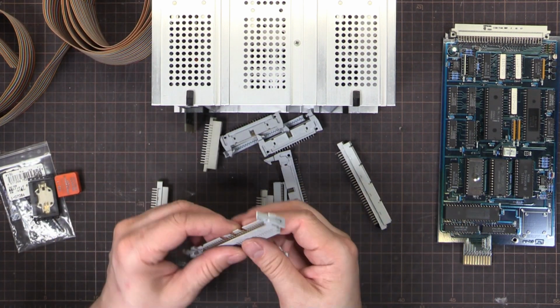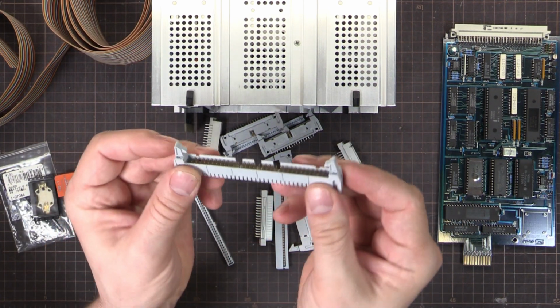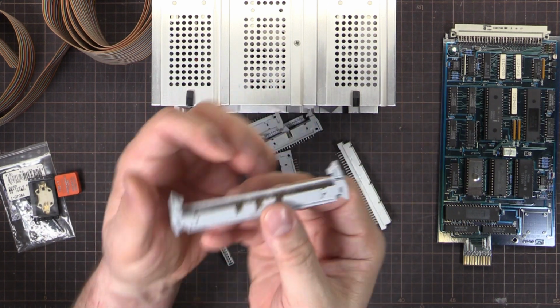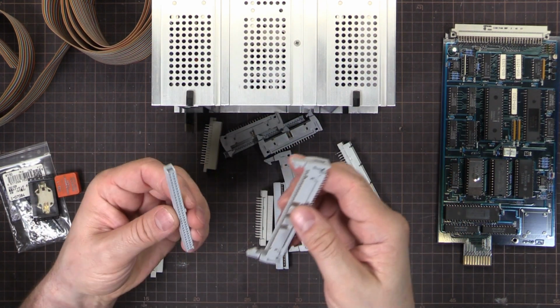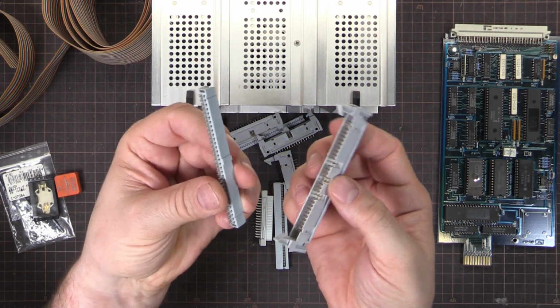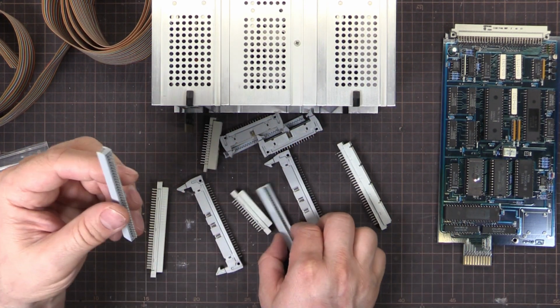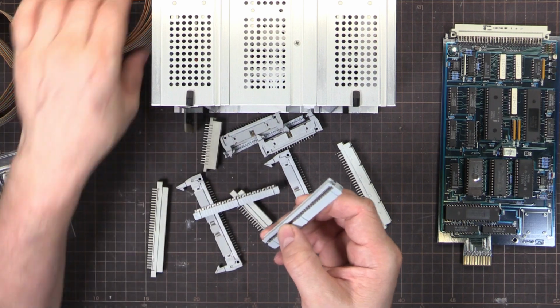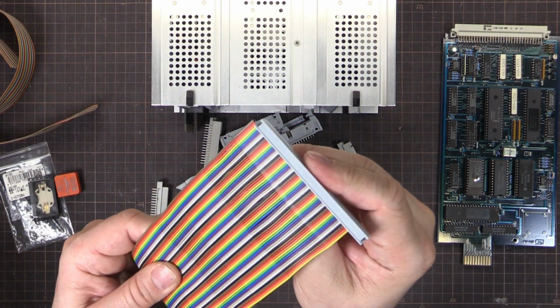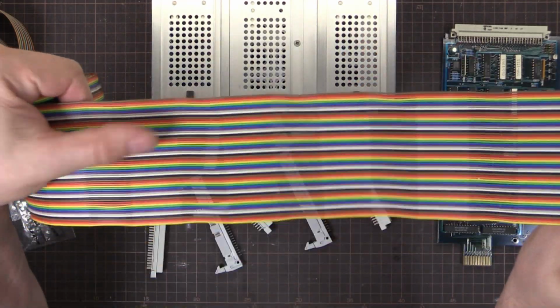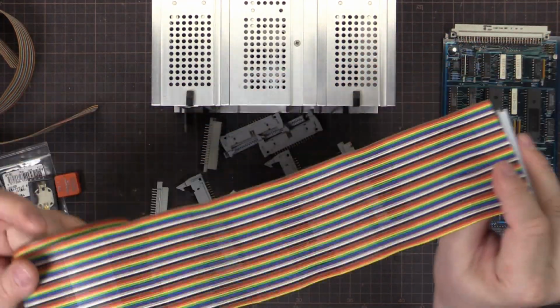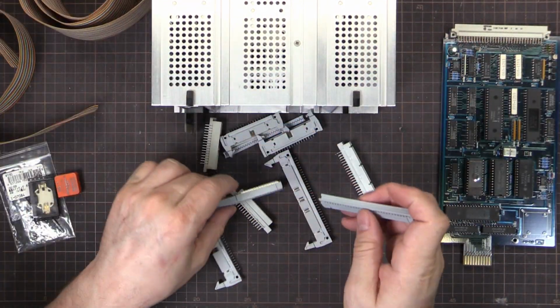I've got your standard kind of connector, like I'm not sure what these are called, just a standard kind of ribbon cable connector, and then that one there is an IDC style insulation displacement connector, and we're going to crimp that on the ribbon cable, one of those on the ribbon cable there, and one on the other end. There's a little trick I'll come to in a sec, and that'll be on both ends.